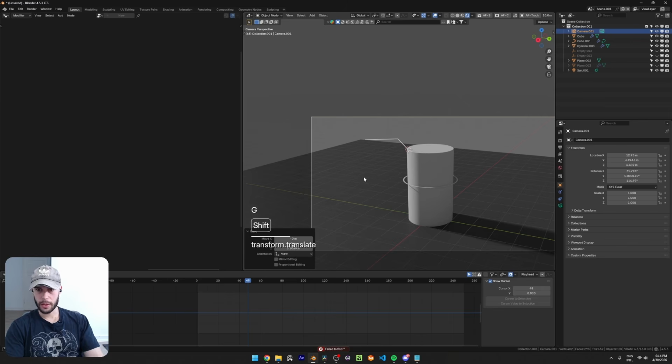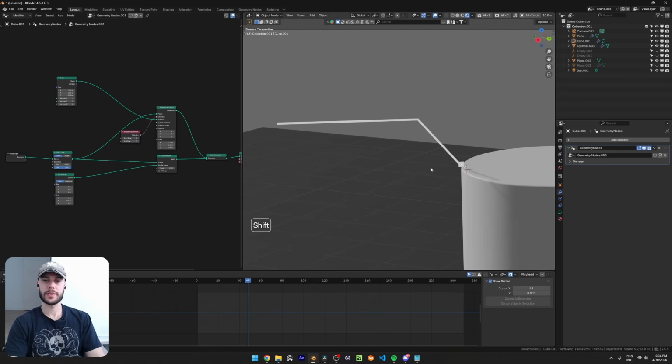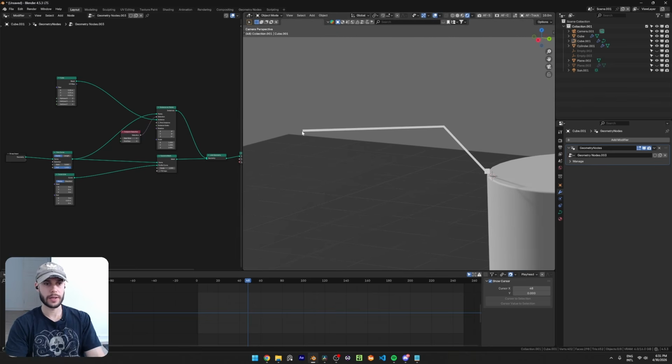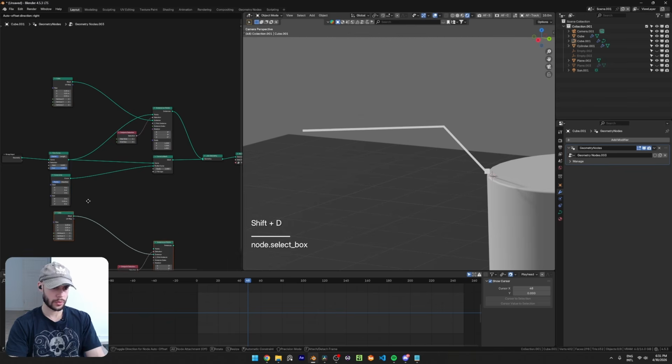So now that we know how to create instances on certain points of the curve, we're going to do the same thing, but for the text. This is something I don't really get to see much, and it's super simple to make, especially in geometry nodes. And we've been talking about the foundations to create such a thing. So let's go ahead and bring this to a whole other level. So now for the text, we want to create the same thing that we did for the point here, but with text on the other end. And to do that, I'm just going to Control D this